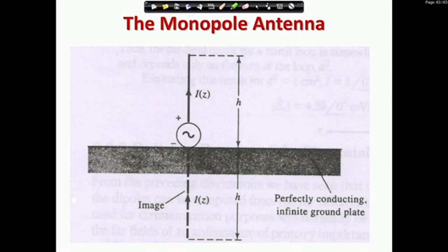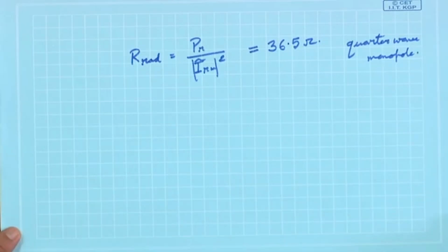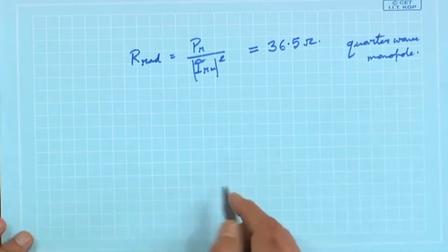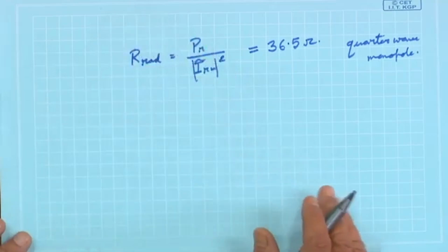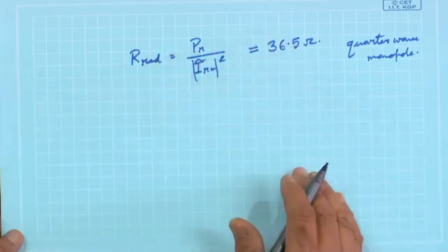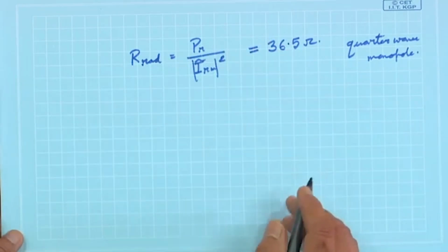Another thing is what will be the directivity, because we have not seen the directive properties of the two antennas, dipole and monopole. But we have all the ammunition for finding that, because we have found the Poynting vector and the total radiated power.